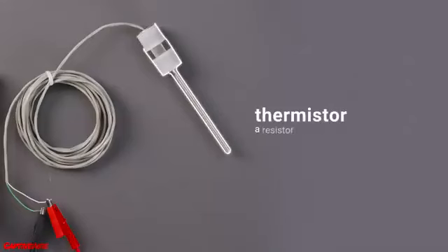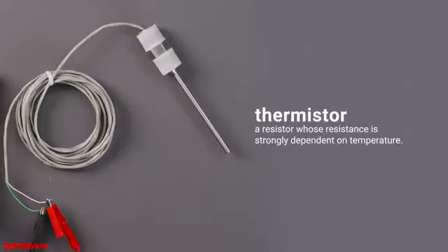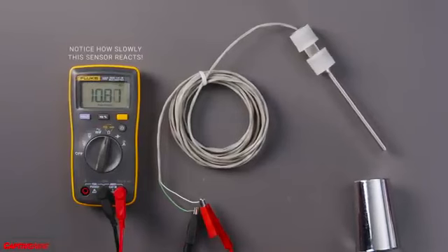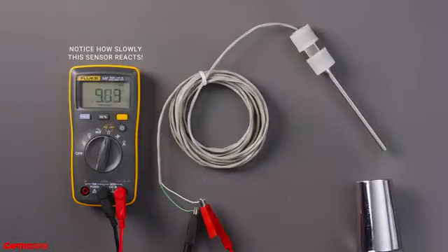But what about something like temperature? I mean, we can't always just have a switch that's on and off. Oftentimes we want to know the actual temperature value in degrees Fahrenheit. So here's a temperature sensor which uses a thermistor, which is just like a resistor whose resistance changes greatly with temperature. At room temperature, the resistance across this thermistor is around 10,000 ohms. But when I heat it up, the resistance goes way down.